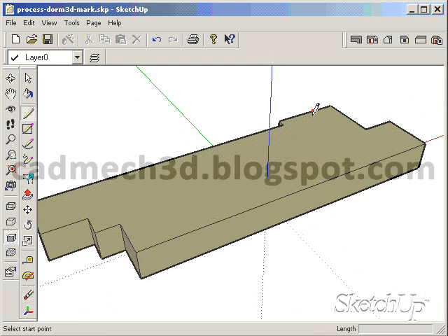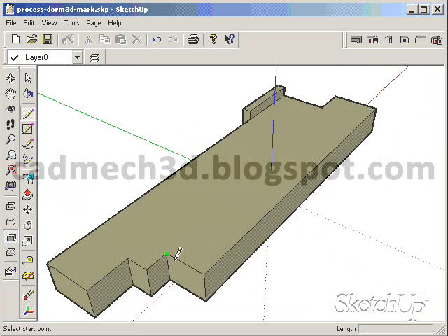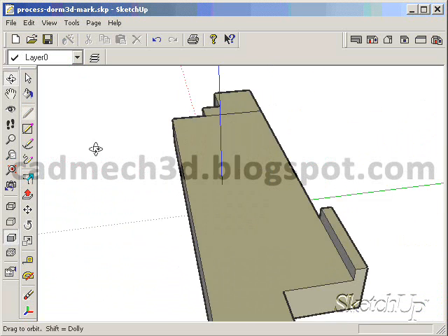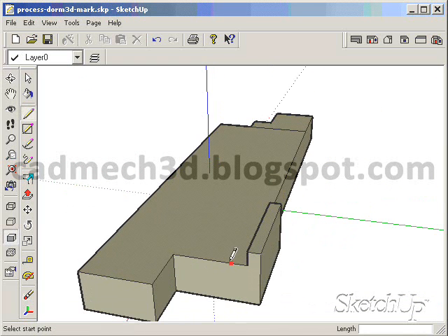Let's make it a little more interesting by making a higher shed roof in this area of the building. I'll increase the plate height by 2 foot for this area. We'll now draw in an edge to define the limit for the main roof volume at one end of the building. Let's orbit around to the back side and draw in the undersoffit for this porch area.